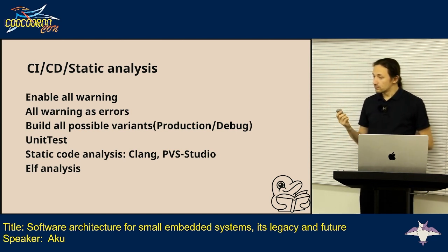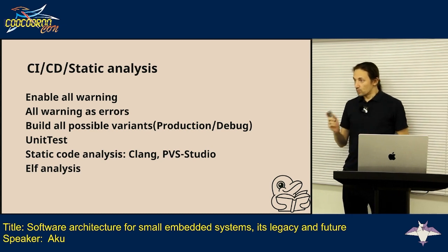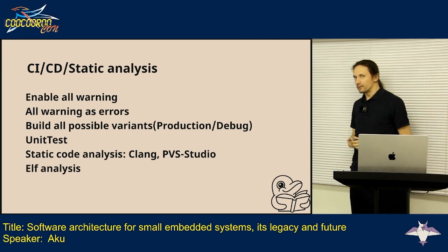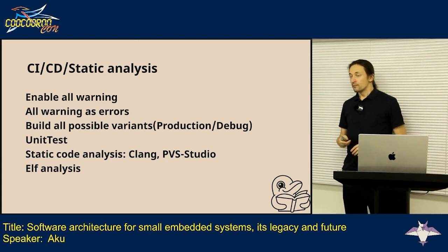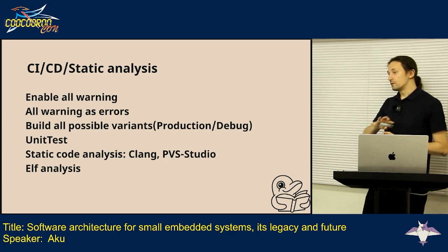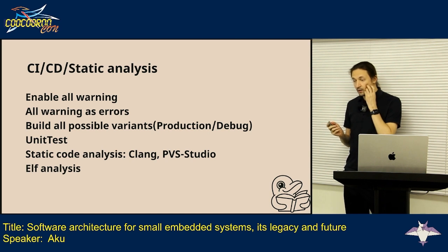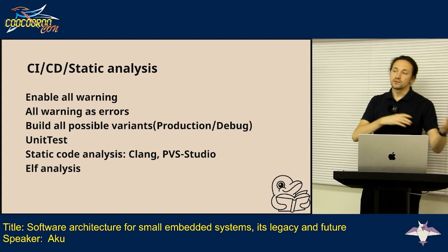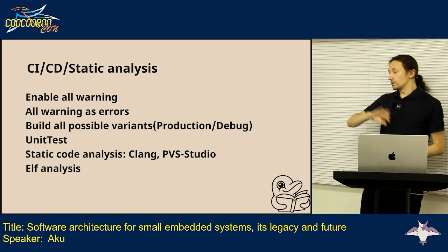And unit tests, surprisingly, you can do unit tests on modern platforms, not on all. Let's say AVR probably will be possible but painful, but with modern ARM cores, it's actually no problem. And you can have a special firmware that has unit test coverage for the whole system, and that's what we're doing. We're covering everything, starting with software synchronization primitives, ending with hardware, and even testing some capabilities. And in addition, obviously, we've got